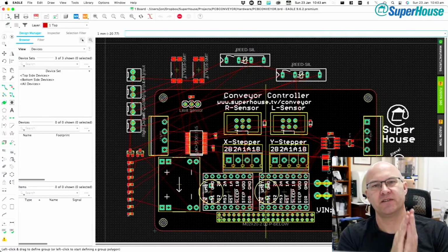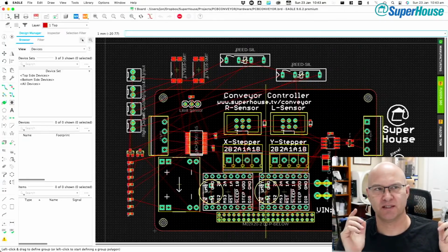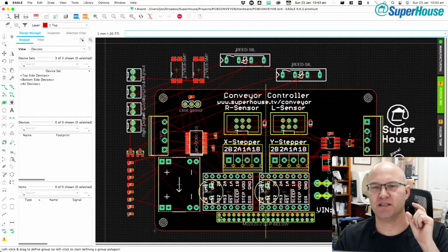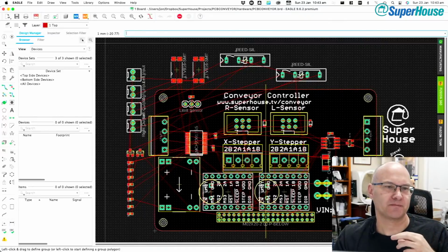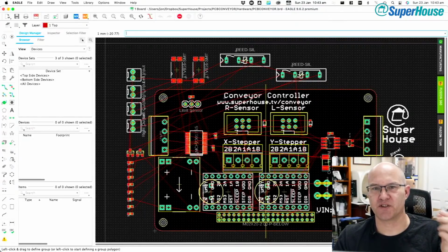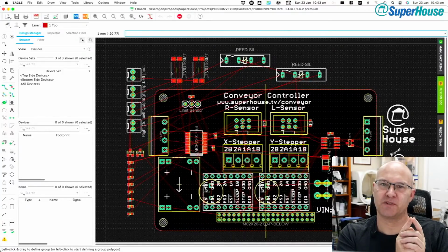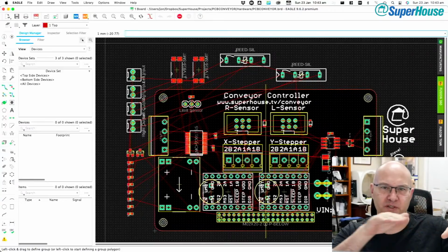Yeah, why not? So my plan originally was to make this conveyor belt system as cheap as possible. So my first design, and what I just showed you, uses little N20 gear motors. I'm using 5 volt, 100 RPM N20 gear motors. They're okay, they're strong enough, they do the job. I can control their speed by PWMing it, and that's working off that system right now. That's okay. But one of the things I want to be able to do is have a PCB come onto the conveyor belt and then move it to a known position.